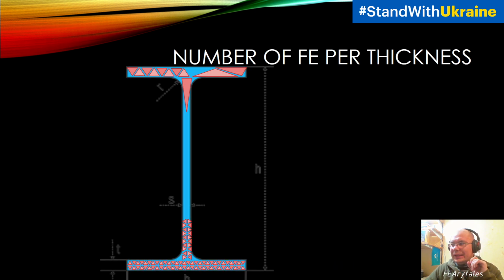And the problem is here. When we talk not about a plate, but about a beam profile, and when we mesh it with a solid mesh, with a tetra mesh, for example, as we see here, we obtain three different meshes. This is the first mesh about which we talk. One element per thickness, but big element. This is second. One element per thickness and same size in all directions. And this is third. And you can see that the number of elements we produce is very, very huge and the difference is very big. So is it really necessary to obtain this?